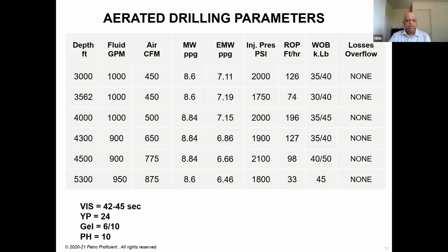water-based mud. So this table is just to give you an idea about what aerated drilling is and what you would normally do. You use your compressor, your booster to get the air, and that is injected along with your fluid in the well in order to achieve lower drilling fluid densities, equivalent mud weight, and basically prevent any losses or get higher ROP. So this is precisely what the objective is.